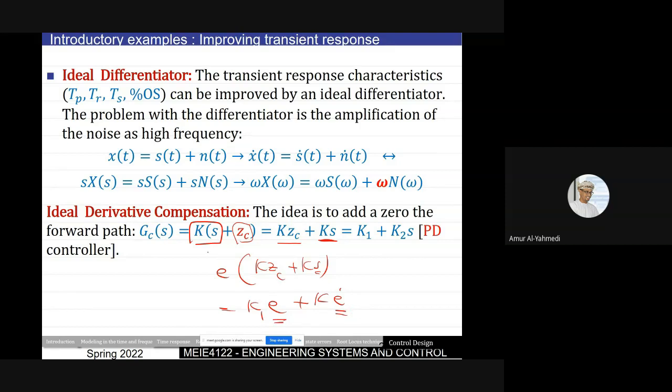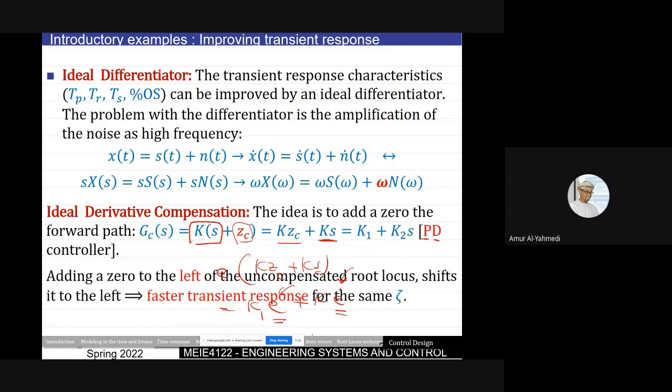So that's why we call this proportional plus derivative. Proportional because of this, derivative because you are taking the derivative of the error. And because you are doing this, you'll be faster because you'll be knowing whether the error is increasing or decreasing. So how to do it?